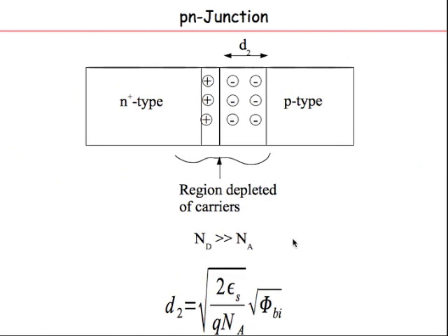There are some equations out here which basically, just based on some basic electrostatics and Poisson's equation, you can arrive at, where you can calculate the built-in potential, you can calculate the depth of these depletion regions and so on.